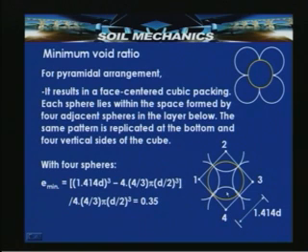in that, if you assume the total volume minus the spheres which are falling within this space represents the volume of solids, that will be 6 half spheres and 8 octants, or 4 complete spheres. So, by taking 4 complete spheres volume as the volume of the solids, the volume of voids to the volume of solids yields the minimum possible void ratio for the pyramidal arrangement in the case of the densest packing.